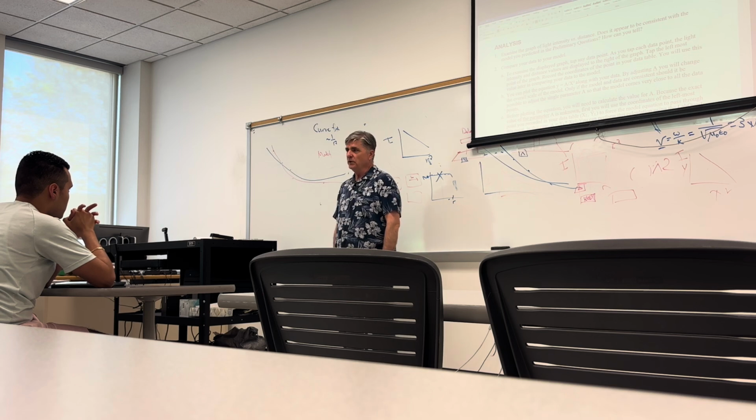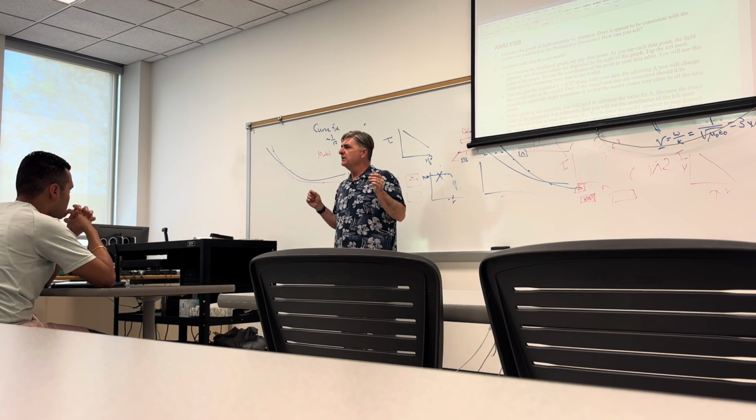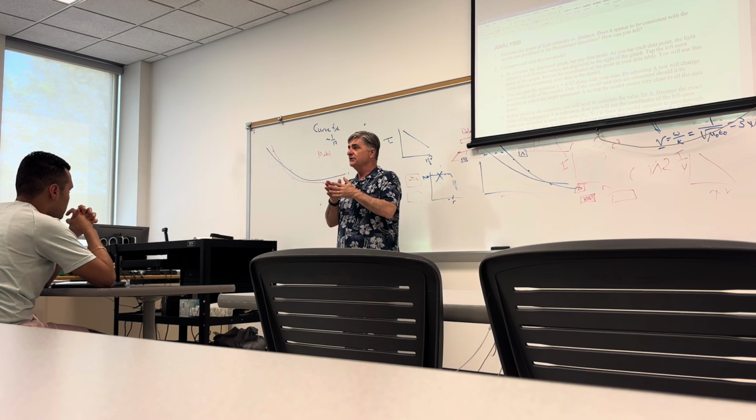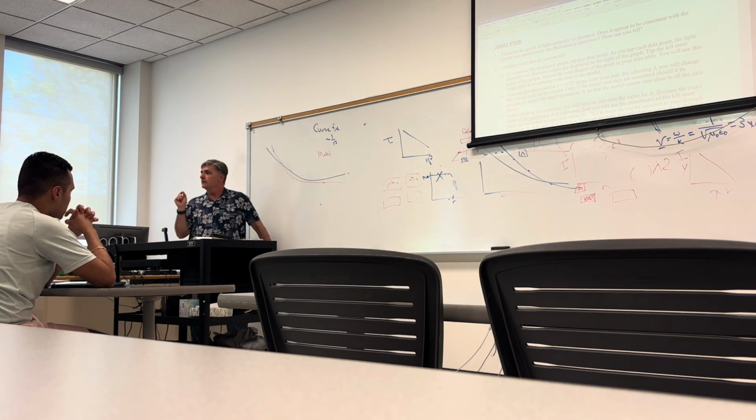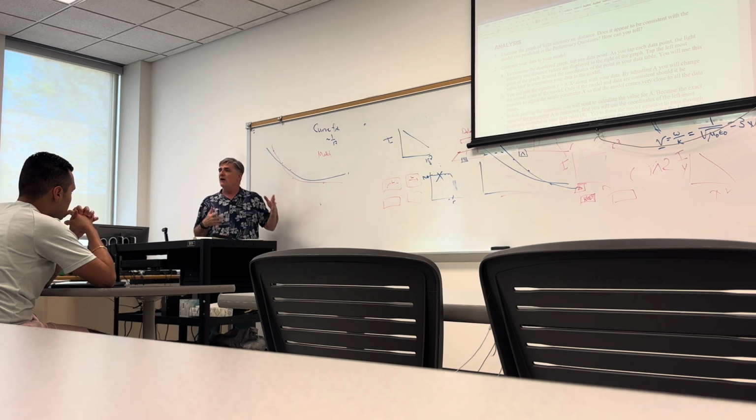But I can't think of a reason other than the fact they probably want to expose you to the fact that there are times when the endpoints are better because you can calibrate right to the endpoint. You have to figure out where to calibrate your instrument. You can't calibrate at every point along the line. You have to calibrate it at certain known values. So maybe you calibrate at this value and this value, so you're saying, those are right. But the calibration's going to be a little off at values in between.